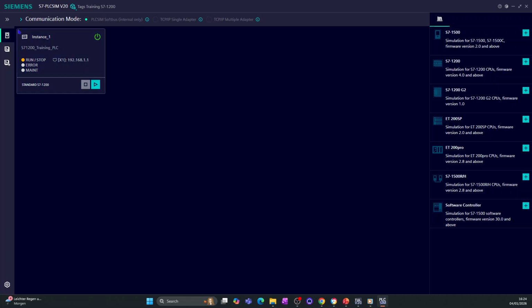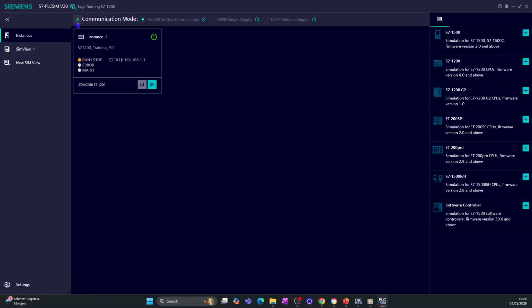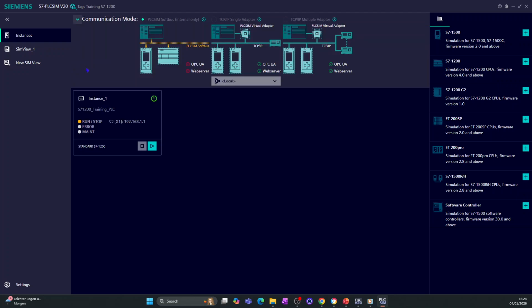And here there are quite a few things I would like you to see. In this module, we can only do the PLCSIM soft bus, which is this. So the PLCSIM soft bus is like a soft bus network that the PLC simulation here has created between devices. We can use that, this is what it has enabled for us here.